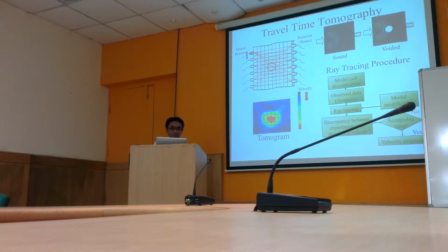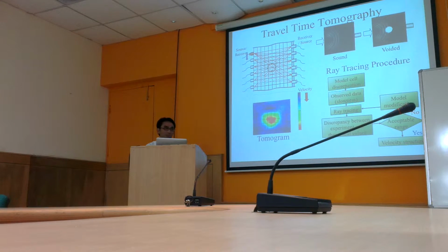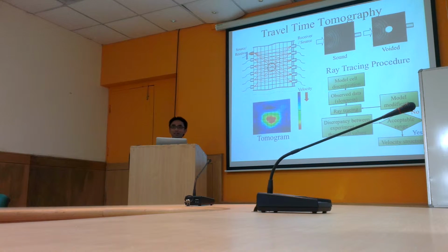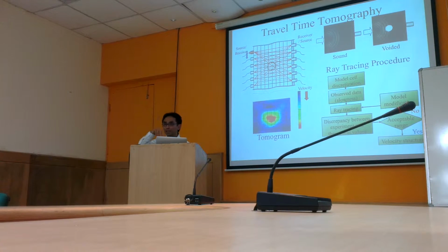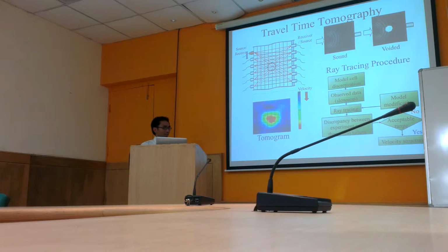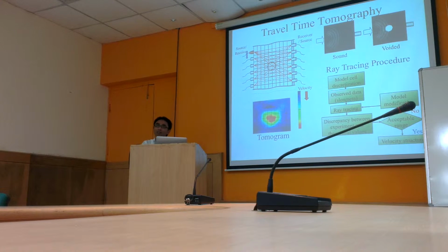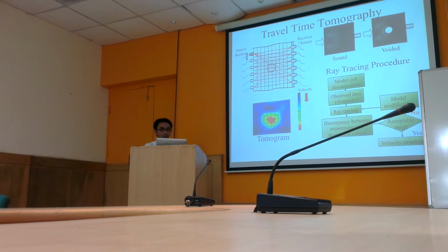It shows that a defect, a void at the center of the model, can be successfully visualized using this technique. And we are actually working on developing some algorithms, because this is basically based on the principles of travel time, wave travel from one point to another point. And we find that there are some issues particularly related to the sensitivity, because the velocity is less sensitive as compared to other parameters such as the shift of the frequency of the wave and also the attenuation, meaning to say the damping effect. So now I have students who are working in developing new algorithms, and we are going to try that out in a few months' time.